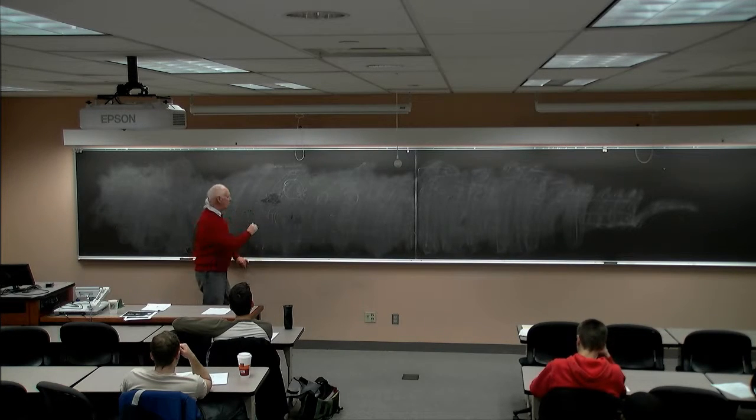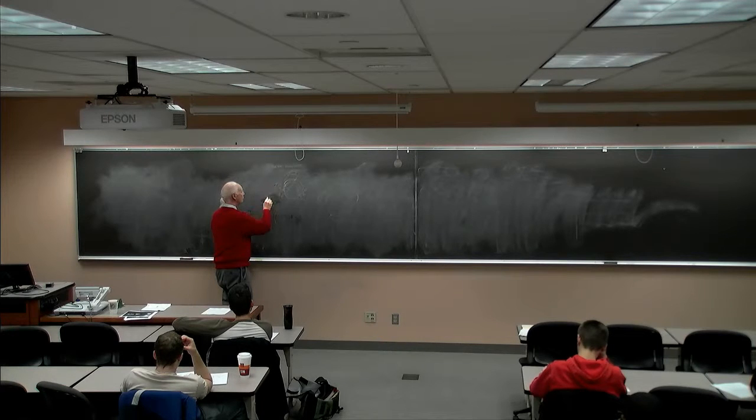It's kind of like a big long loop, and through that loop is a time-varying B field. Guess what that does? It induces in here, Mr. Faraday says, I'm going to induce, in addition to your signal, this is the voice you're trying to hear over here, in addition to that, there is also, plus to minus, a voltage, an EMF, which is undesirable, and whatever is undesirable, we call noise.